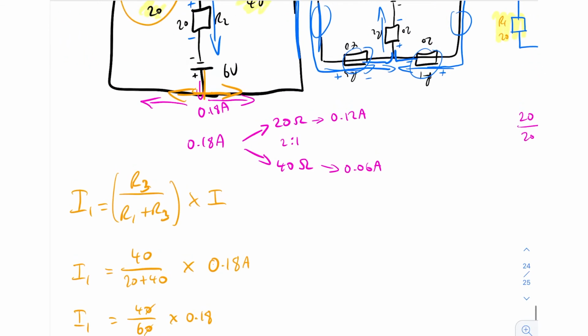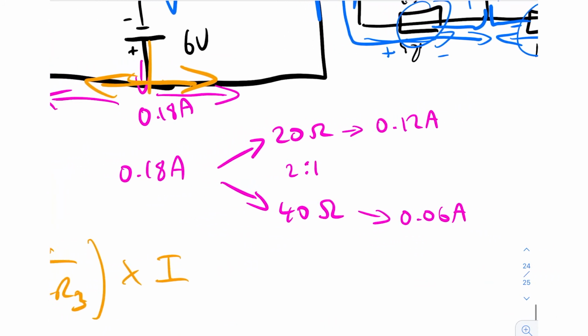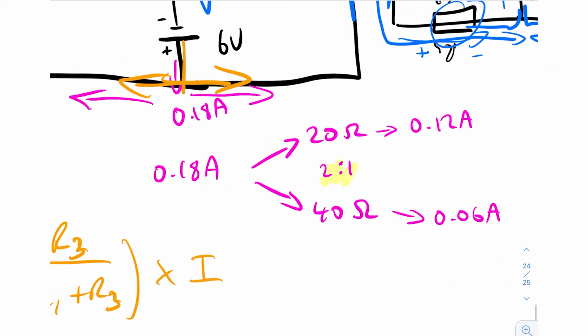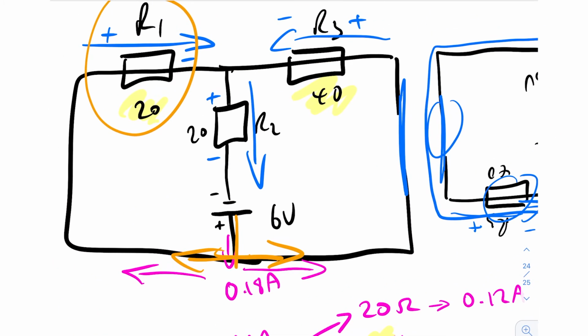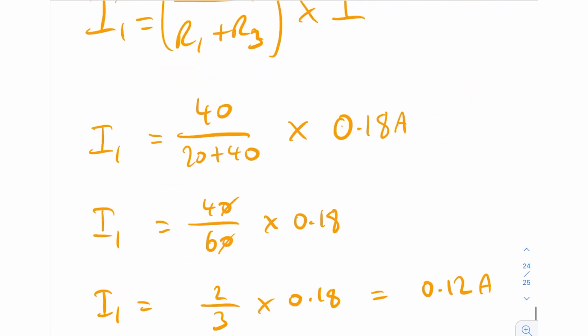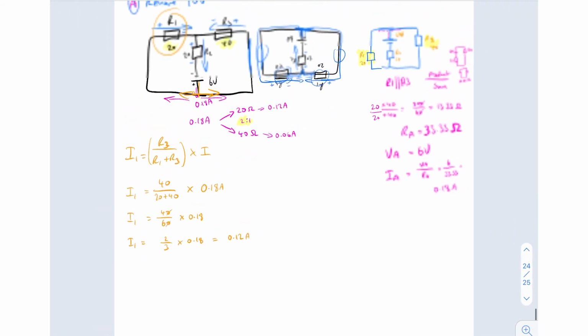And so as you can see here, did the same thing here. So this is like the unconventional way of doing it. You'd get used to doing it like this. Just in terms of ratios, you can clearly see that the current's being split. Imagine if they were both, for example, 20 ohms, you would just know that, okay, the current's being split directly in half. You wouldn't need to do the whole current divider equation, but it's fine. We can do it anyways. It's good revision, isn't it?